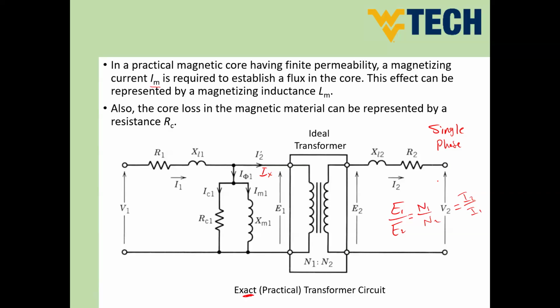You know, guys, also, if we refer a current to another place, it would take the same subscript but with a prime. So if this is I2, the output current here, we can say the input current here is I2 prime. So we can say Ix here is I2 prime. How can I get the Ix or I2 prime? From here. So I2 prime is representing actually the input current, which is referred to here as I1. So I can say this is here Ix instead of I1, okay? Because we have another I1 here in this circuit.